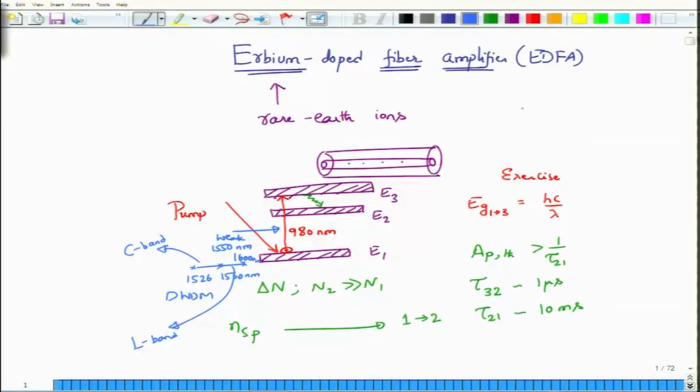They are actually hybrid amplifiers which combine erbium doped fiber amplifiers with Raman amplification to obtain full range of operation from 1500 to 1600 nanometers. These hybrid amplifiers are the ones used to simultaneously amplify all of the WDM channels that are located anywhere between 1500 to 1600.